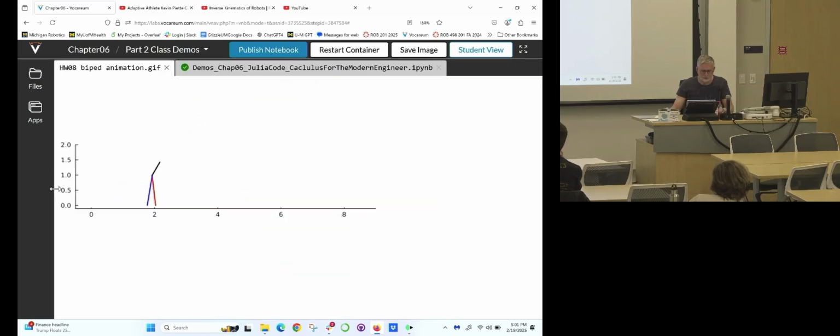Okay. So this robot doesn't have knees, so it has to drag its feet when it's walking. Okay, so you add knees, and now you've got twice as many motors, and instead of having 120 variables, you'd have 240. Okay, then you add the ankles. Now we're up to 360. And now we let the hips go out in the plane. We've got 2 more joints. We're at 480 decision variables.